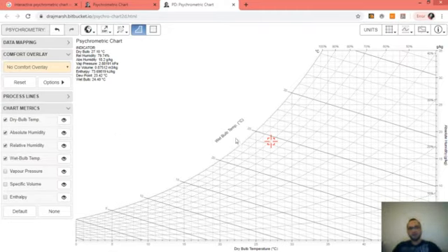As I have mentioned in class, the wet bulb temperature is the temperature measured at saturation when you have relative humidity 100%. For example, if I locate the pointer here, a climate condition with 44 degrees Celsius dry bulb temperature, which is the atmosphere temperature, the air temperature, and a relative humidity 100%.